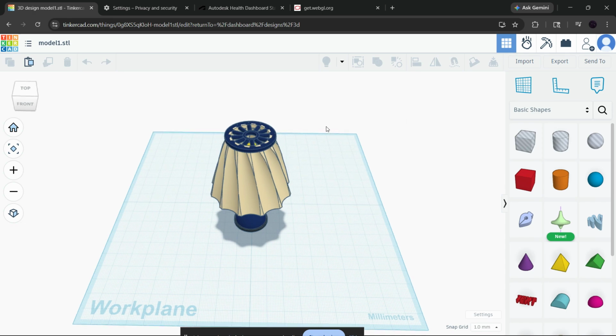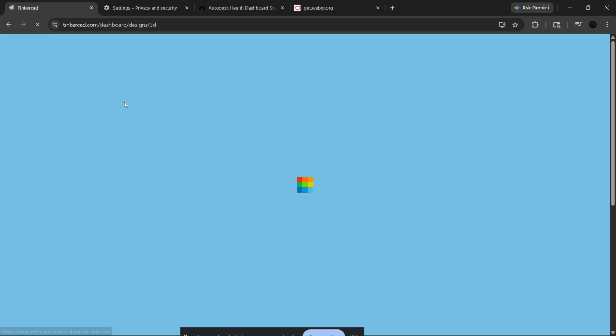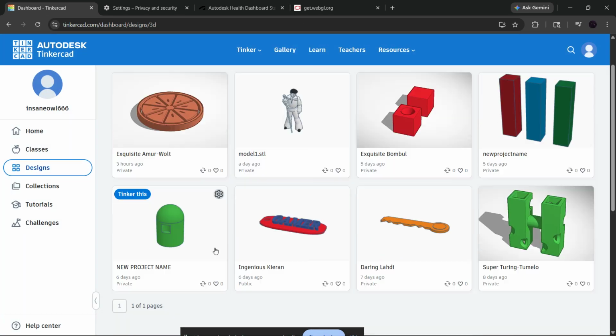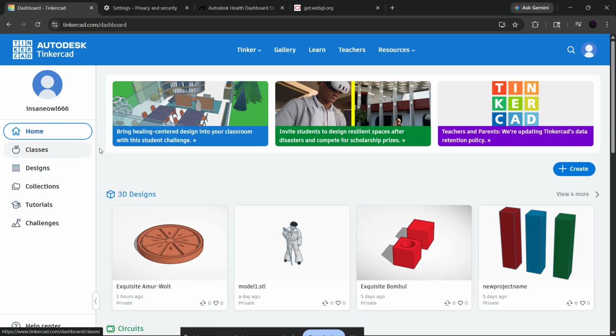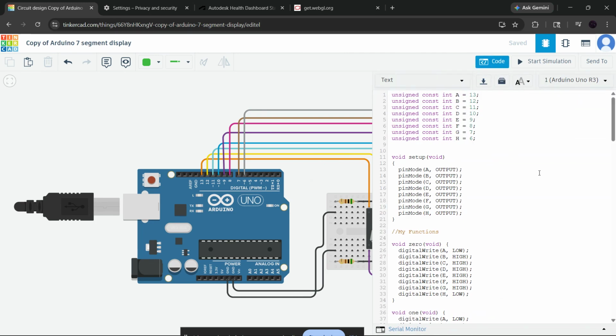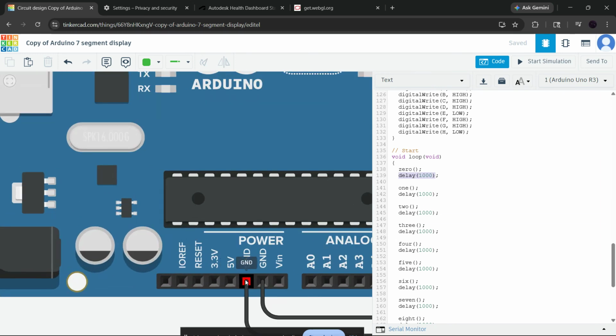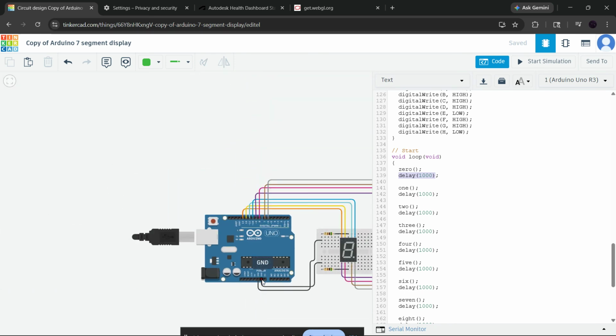If you are working in Tinkercad circuits, circuit simulation errors are often caused by code or wiring issues. One common problem is an infinite loop. If your sketch contains a while loop or a loop function that never pauses, the simulation can freeze your browser tab. To prevent that, make sure your loops include a small delay, such as delay 10. Another important thing to check is for short circuits. You should never have a direct connection from 5V to GND without a component in between. A short circuit can crash the simulation engine or stop the circuit from running at all. Double-check your wiring, then rerun the simulation.